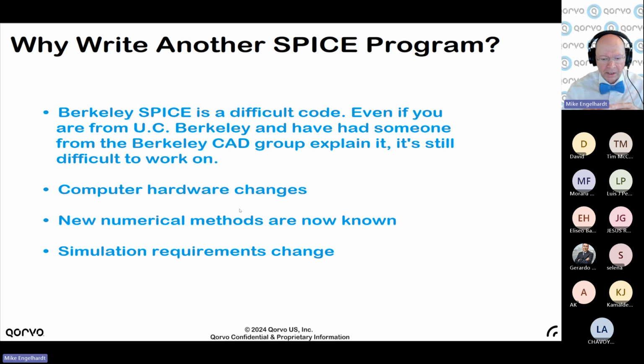That doesn't take one clock cycle. Each clock cycle is a couple hundred picoseconds; for a 5 gigahertz processor, it's 200 picoseconds. It doesn't take one clock cycle, but today it takes only 3 latent clock cycles at the end of the pipeline in the floating point unit to multiply two 64-bit numbers to a 64-bit accurate result. That means you can do it in a small fraction of a nanosecond.